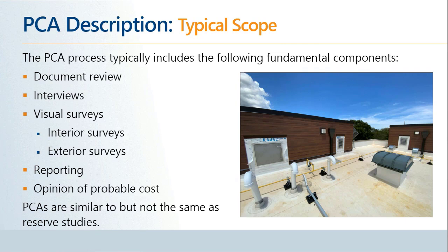On-site surveys include both interior and exterior visual surveys. The surveys are almost exclusively limited to exposed conditions, and they're typically made from grade, sometimes with the aid of binoculars, and are also made from balconies, setbacks, and other areas that allow for a more detailed review.